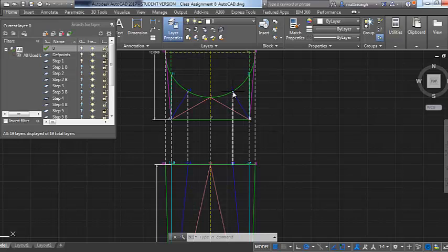Even though I use these to develop the actual true lengths, in reality, this might be too far of a distance to press break that far apart, and I may need to add additional press breaks. I don't really have to modify my part to do that. I can just do that on the press break as long as the part has actually been formed by using true lengths. It'll be close.